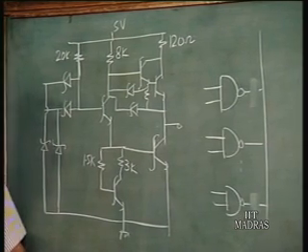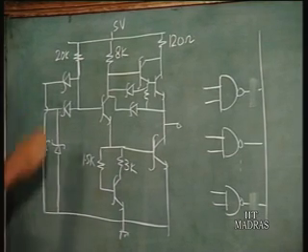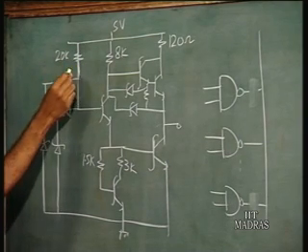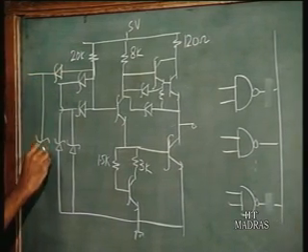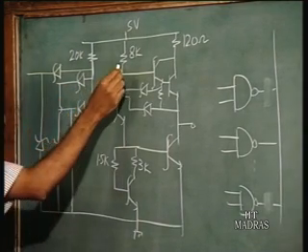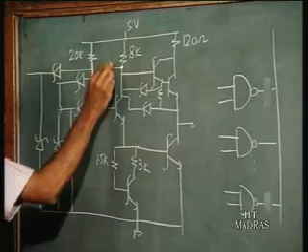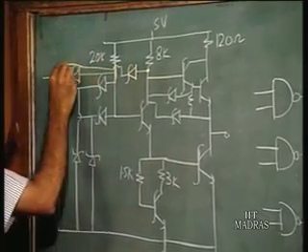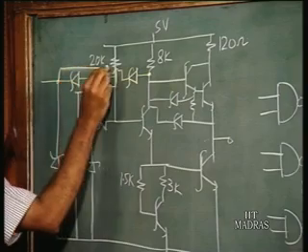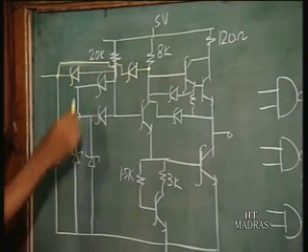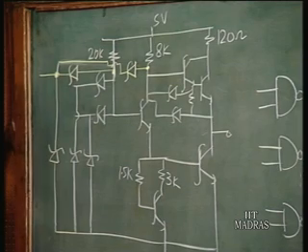Neither is it going to source current nor is it going to sink current. So, how do you do that? It is a very simple alteration, or a simple addition, additional components are required. What you do is you have another input here, a diode here, just like this one, and there is another diode coming from this point here. It joins up with this input here. So, you have 2 diodes here which are connected to this common point. One is connected at this point here and the other is connected at this point.